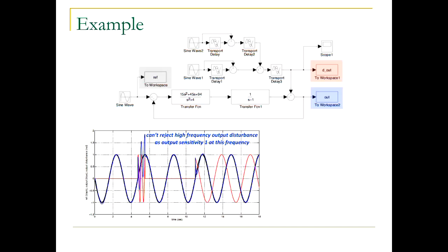So we turned on the high frequency signal, but then we set it back to 0. Now again the disturbance is 0, and note that again the thin blue line converges to the thick blue line very quickly. So again we are back to the scenario that the controller was designed for. And then at this point here, about 11 seconds, we hit the system with a sinusoidal disturbance of the same frequency 2.